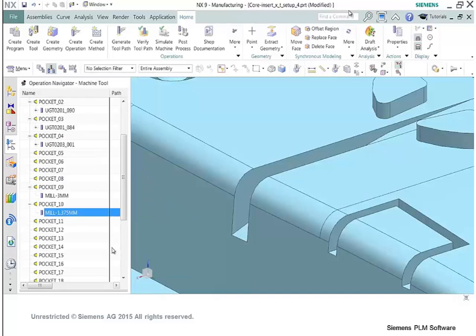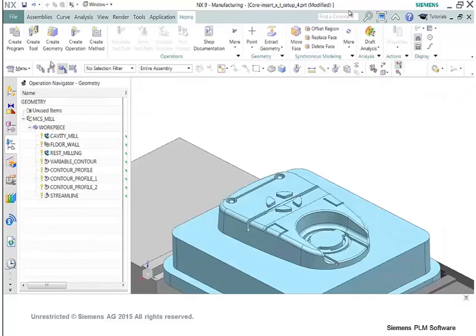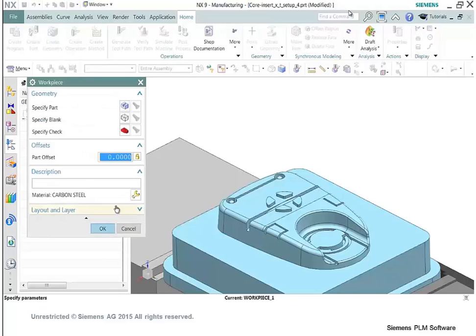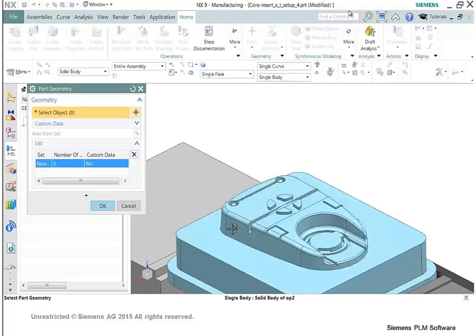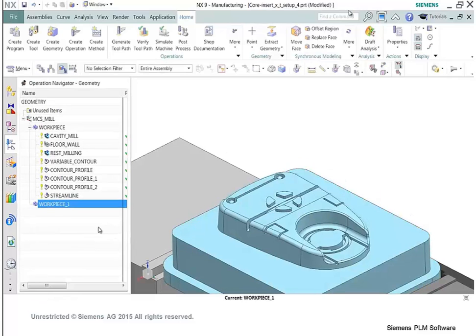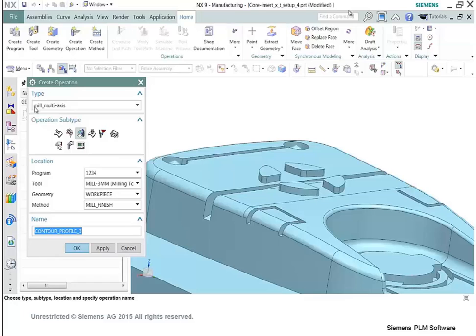You can create tools in the pockets where they belong in the machine. You can program the entire part that way, just underneath each tool. So here we go. We're going to pick our part, tell us what our part is. That becomes our part, our new workpiece. In other words, our operation 2 workpiece. They all belong to that same machine coordinate system. They all have that same common piece of stock, right, for what's remaining on the part.